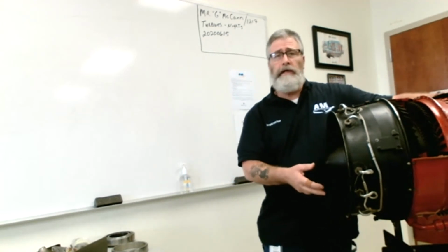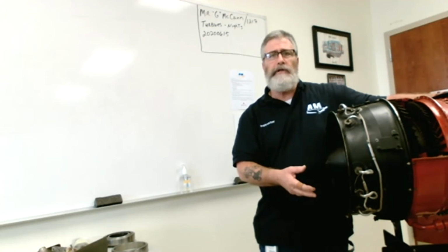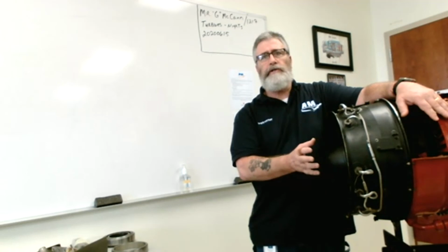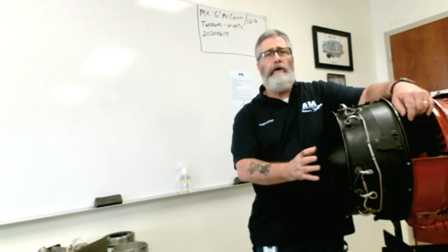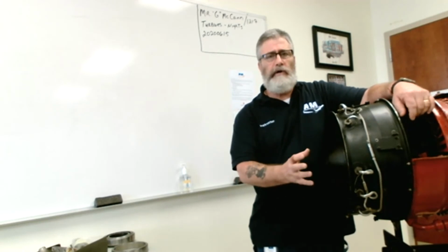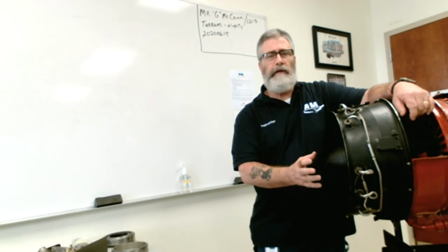Afterburners are capable of accelerating the aircraft 100% faster than its original speed, but for only short periods of time. It utilizes its own fuel control because we still need the main engine to be running normally. We don't want to rob the fuel from the main engine. So it has its own separate fuel control that sends its own fuel source, and it can only be used for short bursts of time, or else the aircraft would simply run out of fuel. Also, it's extremely hot, so it does cause some damage to the exhaust section, all right?